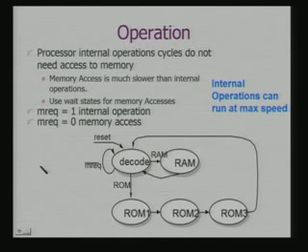That is something which is important. Wait states will get inserted only when the processor explicitly requests a memory access. So, that is the basic significance of this MREQ signal which is coming out of the processor. MREQ 0 clearly indicates a memory access, and MREQ 1 is an internal operation.